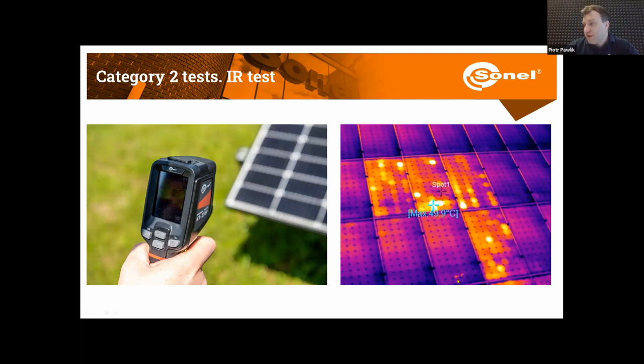But we can also see sometimes things which are just dirt. It could be some physical dirt, like, for example, bird droppings, maybe some leaves which are falling on the installation, or some other dirt. Here we can easily notice this with a visual inspection with our eyes and very easily fix the problem just by cleaning the panels.